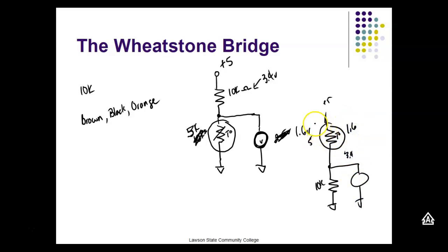So here, as the temperature goes up, the resistance goes down. This guy's going to drop less. This guy's going to drop more. So if I wanted it to act like a PTC, I just do what? I just put my fixed resistor on the bottom, or take it across my fixed resistor. So like I said, I've never seen a PTC. I've never seen one. But I can look at Jameco. I've never ordered one. Let me rephrase that.